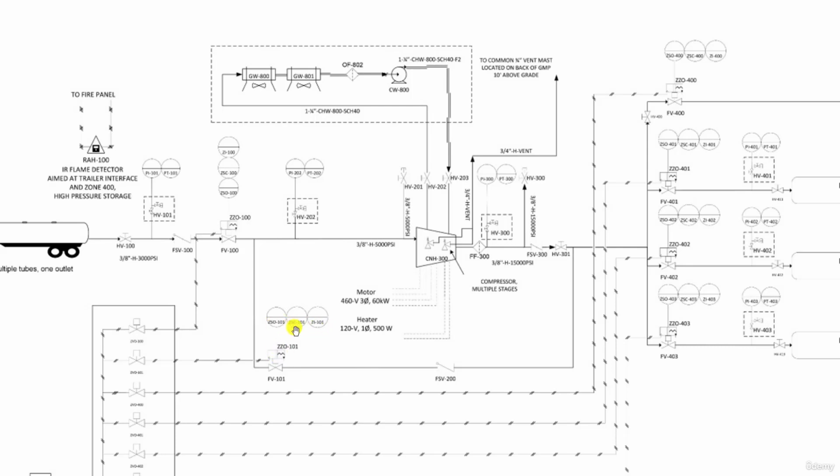On this bypass line, you have a flow valve FV101, which is also air actuated with spring return close and equipped with limit switches. On the suction line of the compressor, you have a process connection to a second set of pressure instruments, PI202 and PT202. This is to monitor the pressure on the suction side of the compressor. Here again, these pressure instruments are not involved in a control loop or in a safety loop.